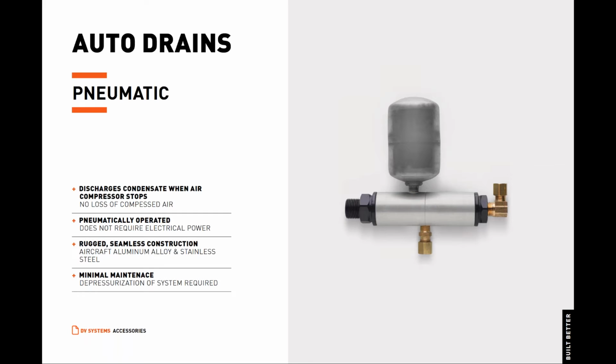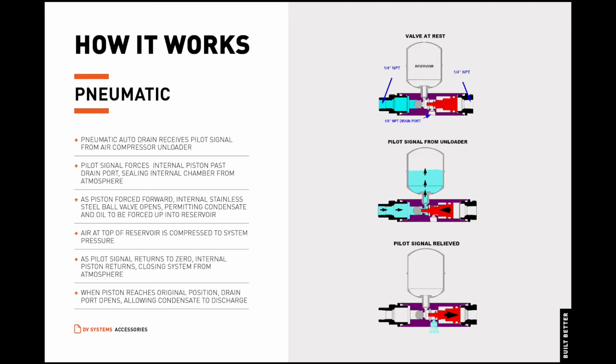These pneumatic auto drains come standard with an XL package. A factory-installed model is available, model number AD-9400MTD. A field-installed model is also available, model number AD-9400. A repair kit is available, RK-AD-9400, and contains the internal piston, O-rings, gaskets, and screens.